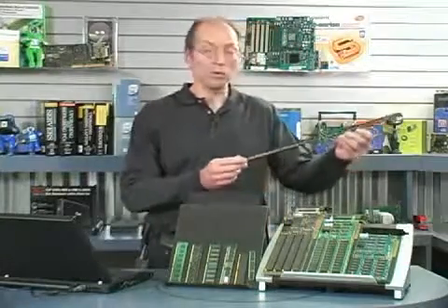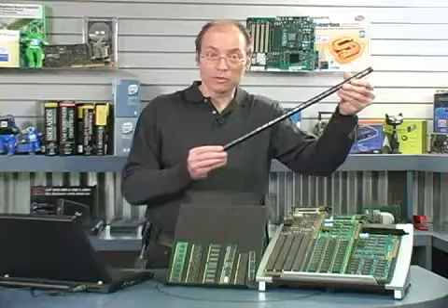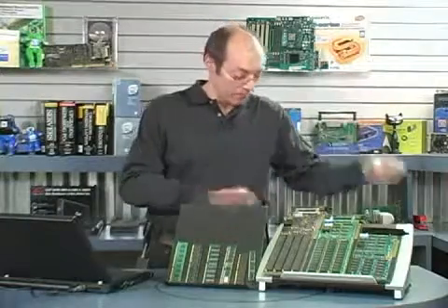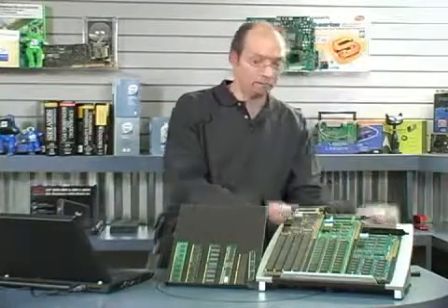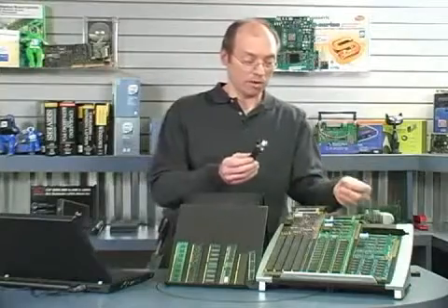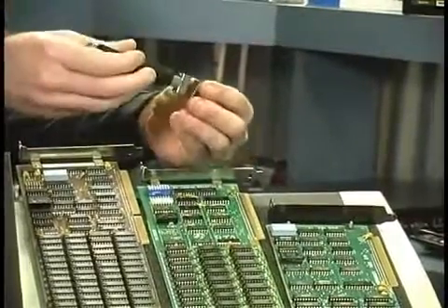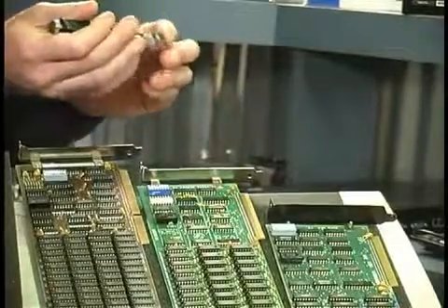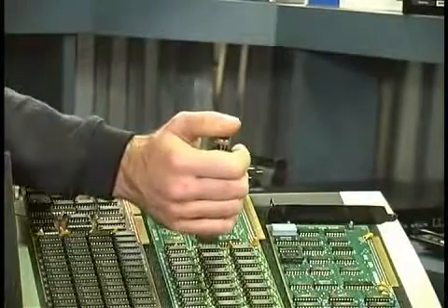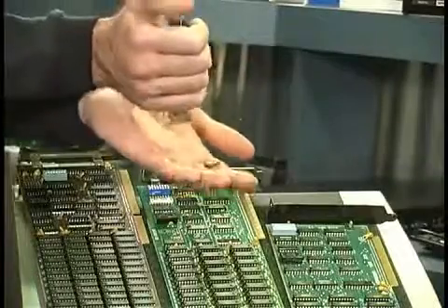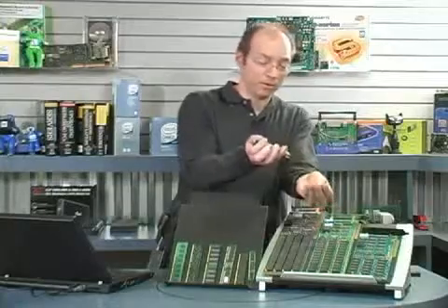Back then, what we had to do was buy chips. They usually were sold in these little tube-like containers, and you would take the individual chips out of the container, like this. This is one of the memory chips. We'd load it into a memory insertion tool, like this, and then you would use this tool and put it over the socket, and then press down and push the chip into the socket using this tool.